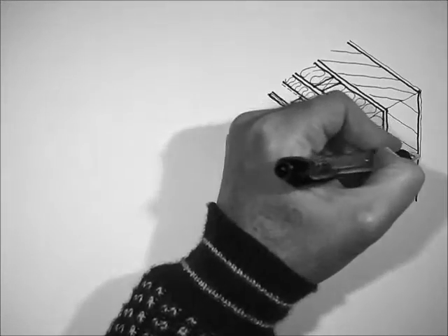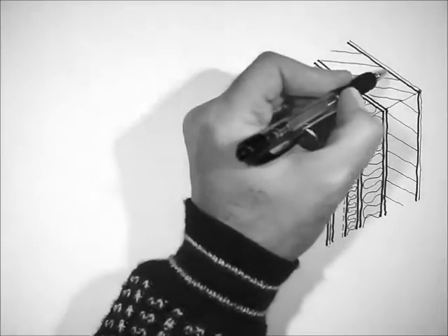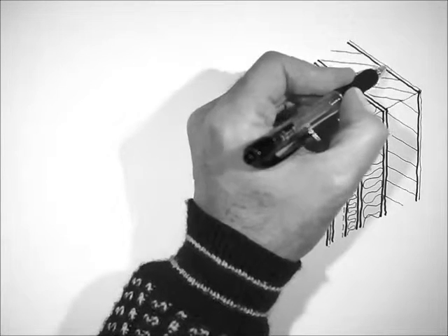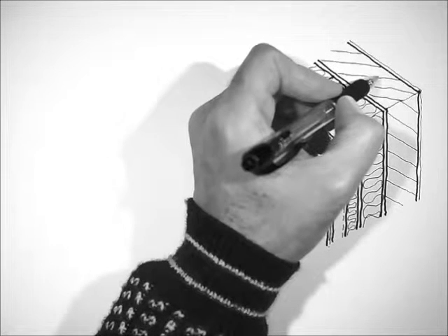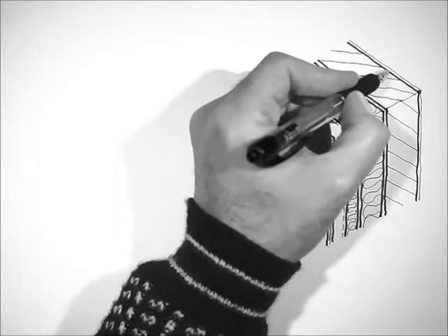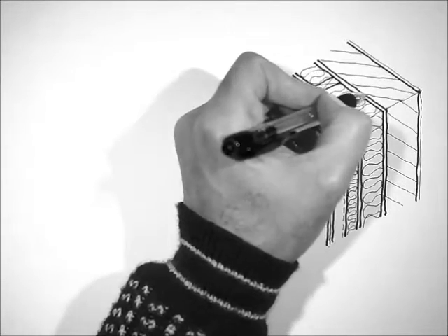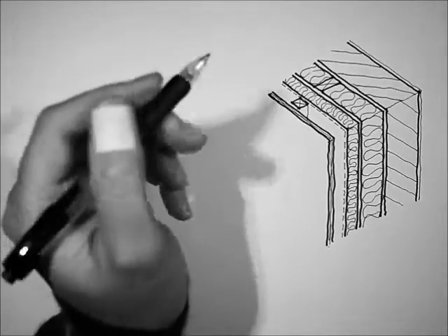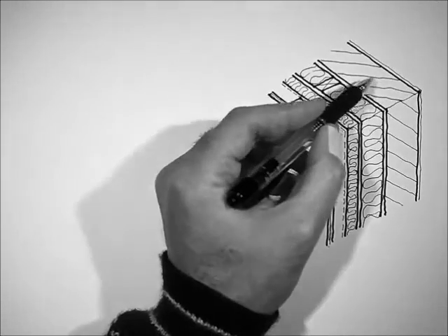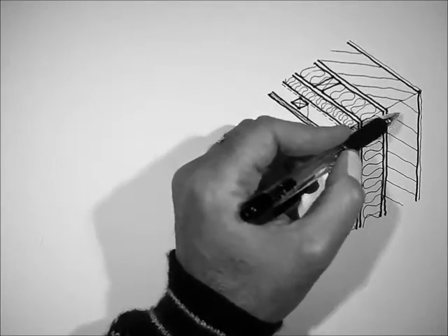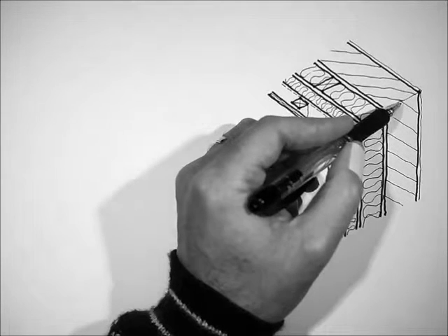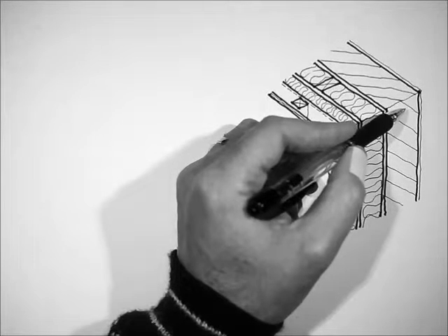And I say wet plaster as opposed to plasterboard because wet plaster bonds directly to blockwork without an air gap, which means the plaster and the block contribute to the thermal mass of the building. The blockwork represents the structural zone of the building.